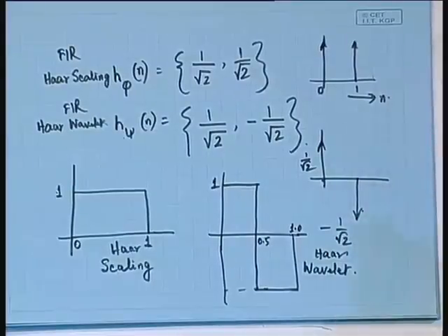Conceptually it matches, because any low pass filter would basically mean averaging, and any high pass filtering would mean a differentiation, and differentiation in the discrete domain is just a subtraction or difference in the discrete space. So this is what we will be obtaining, and in fact, a still image compression system uses this wavelet in a big way.